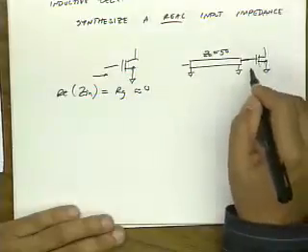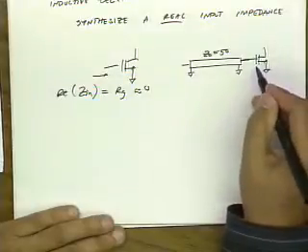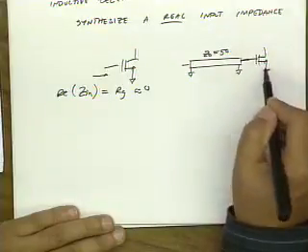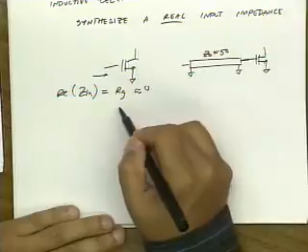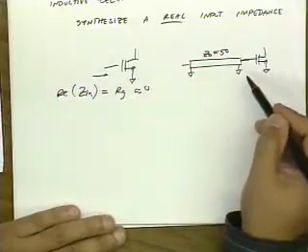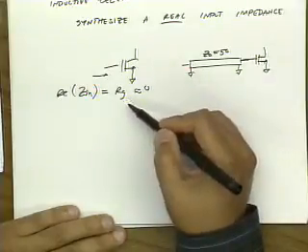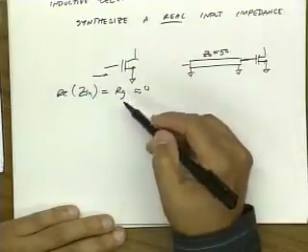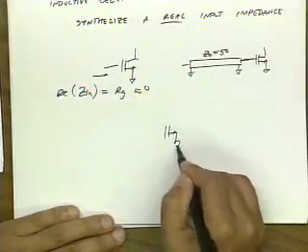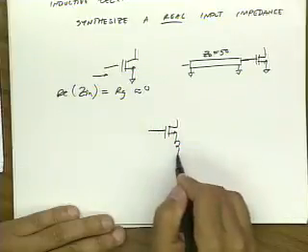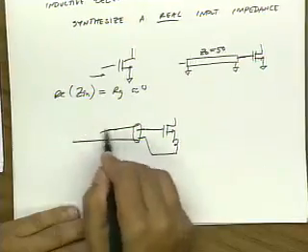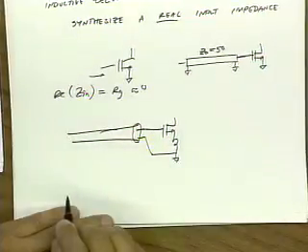Transistor on its own is going to look like a capacitive termination. Another way to look at it is if I want to extract the maximum power gain of this transistor, I want to drive it with a source impedance which is the complex conjugate of the input impedance. Well, RG is the real part of the input impedance, which is very small. Let's say this is 1 ohm. It might not be possible to drive it with a 1 ohm source. So inductive degeneration lets you raise the input impedance to any value that you want.